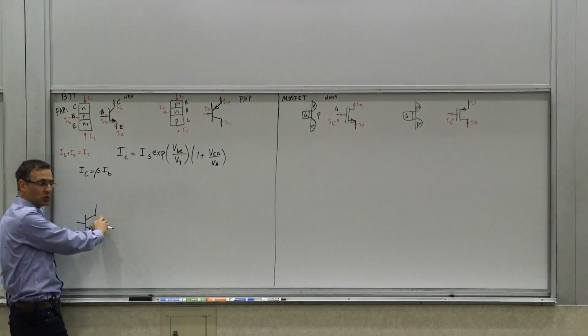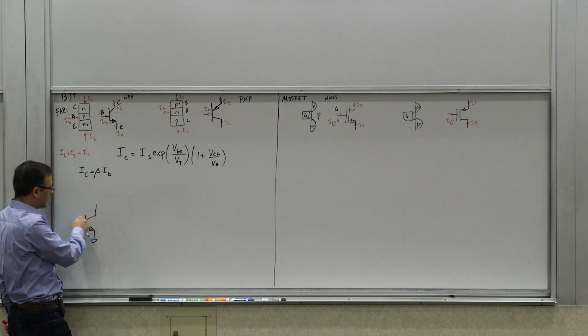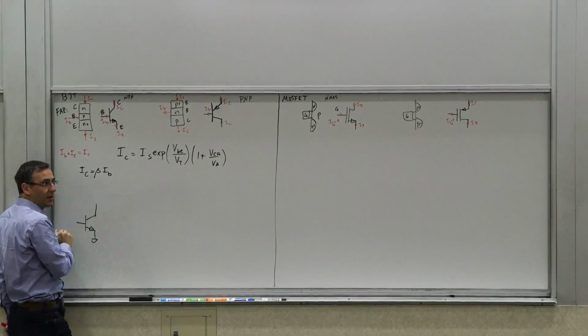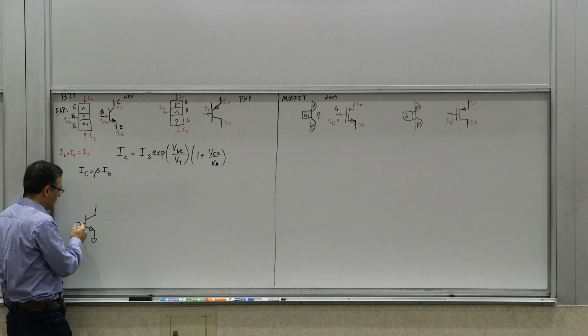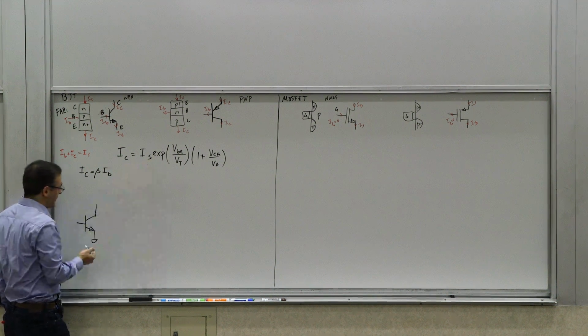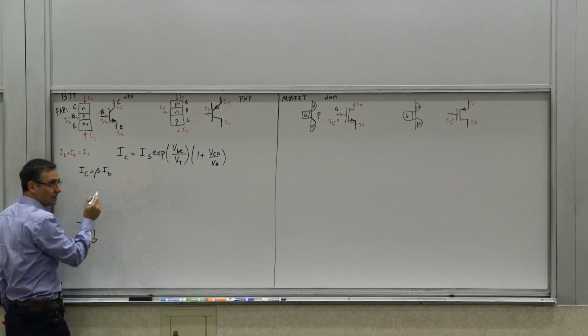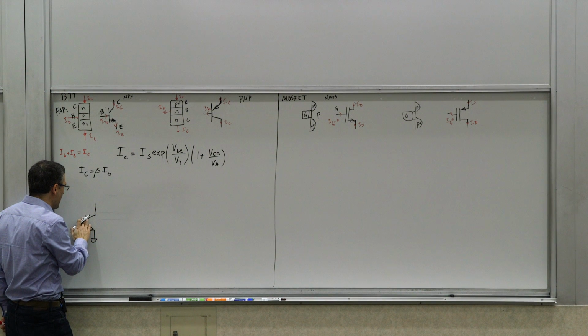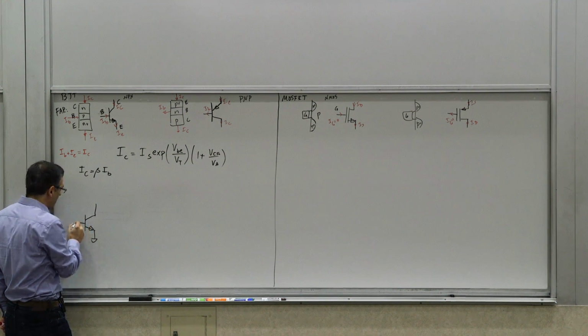But once you get to 0.2 volts, you're basically starting to forward bias this junction, and you're leaving the forward active region, so this doesn't even hold anymore because of all the interesting things we talked about in the device physics, which we'll come to from time to time.